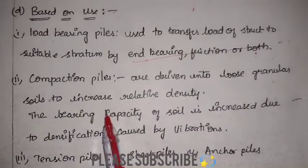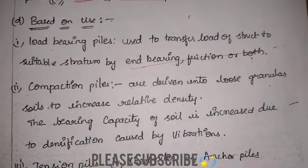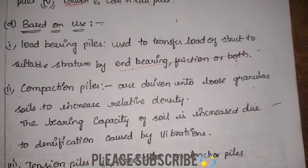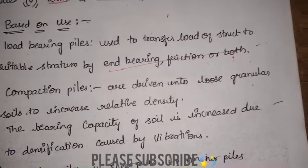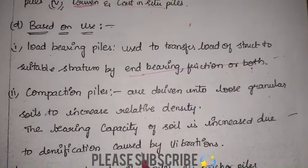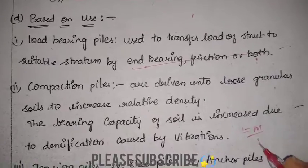Next we have compaction piles. Whenever you have a loose granular soil, to increase the relative density we sometimes compact the soil. The piles used to compact the material are called compaction piles. The bearing capacity of soil is increased due to densification caused by vibration. We know density equals mass by volume.